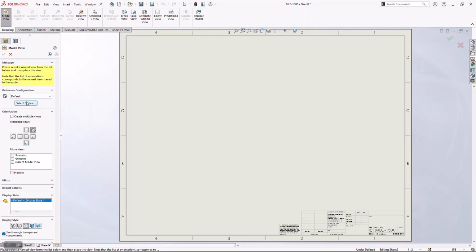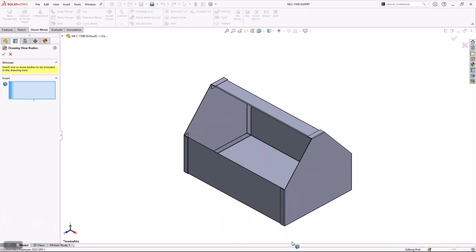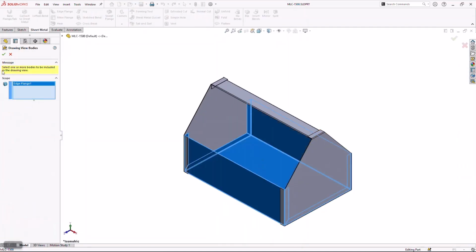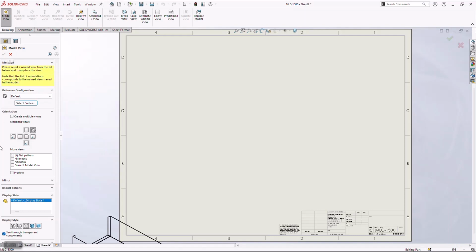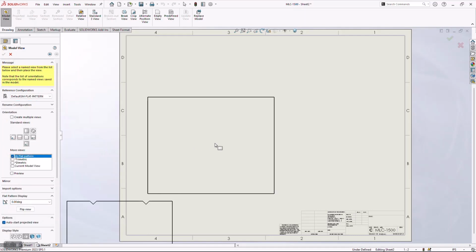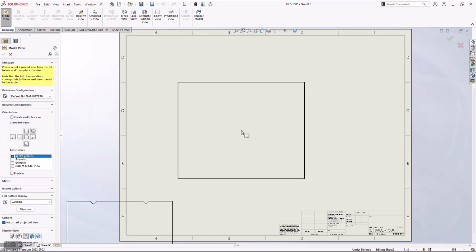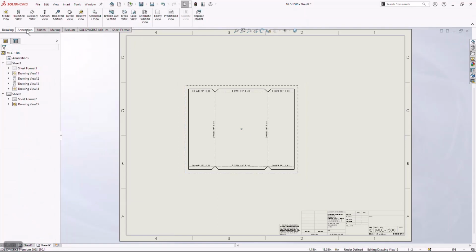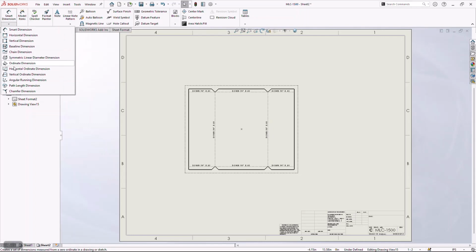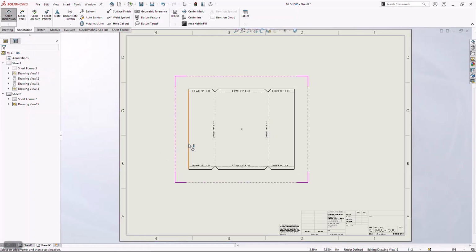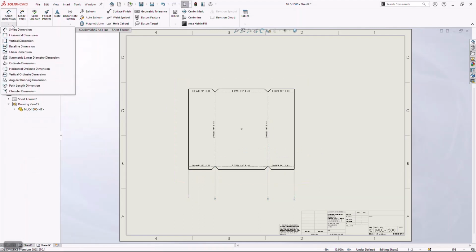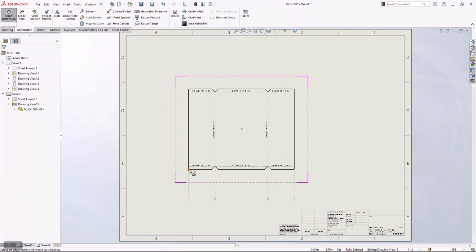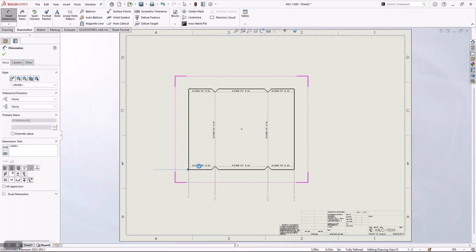But you will notice that I have this option called Select Bodies. This gives me the ability to define a scope which they can flatten out, which turns this into essentially a standard single body flat pattern. At which point I can add my manufacturing information. A lot of the times I like to leverage an ordinate dimension, and I can detail out all of my bend lines so my press brake operators can now come in here and calculate their backstop gauges.